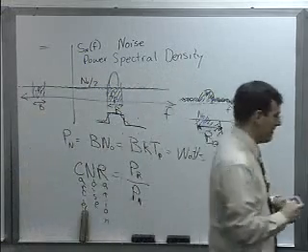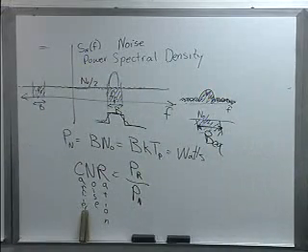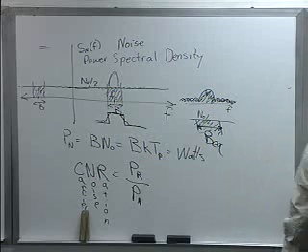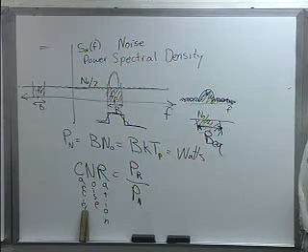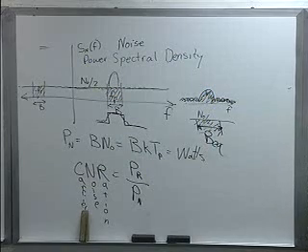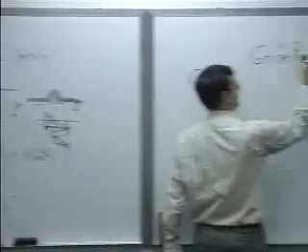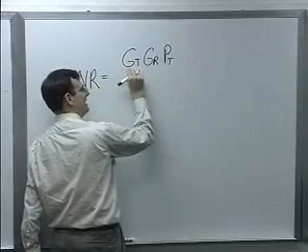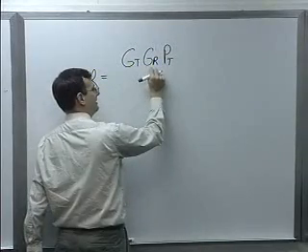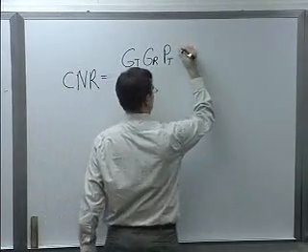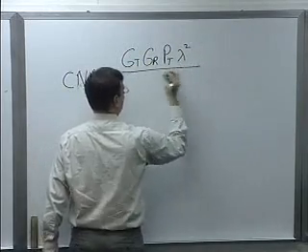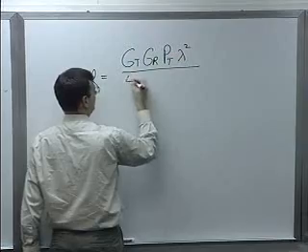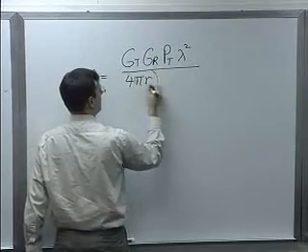Another point I wanted to make, and this happens a lot in satellite communications. Remember, for that carrier to noise ratio, we said the top is the link budget: G sub T times G sub R times my transmit power, antenna gain for transmit, antenna gain for receiver. We've got a lambda squared, and 4 pi R quantity squared.